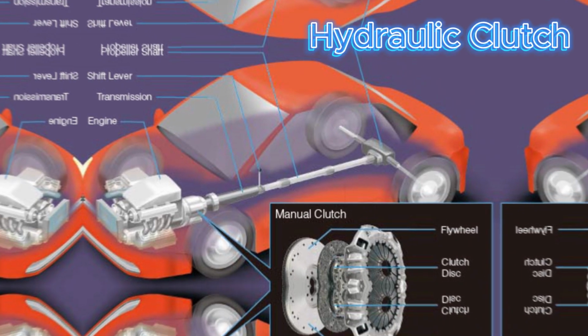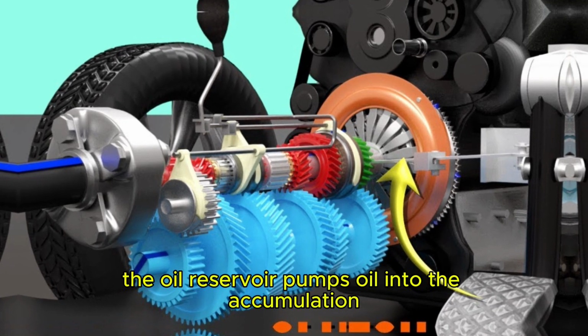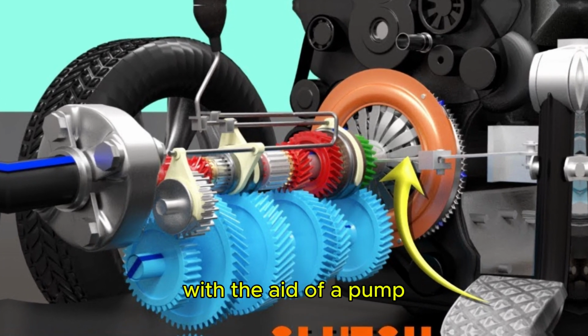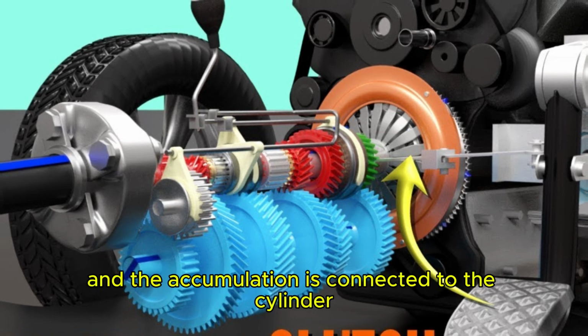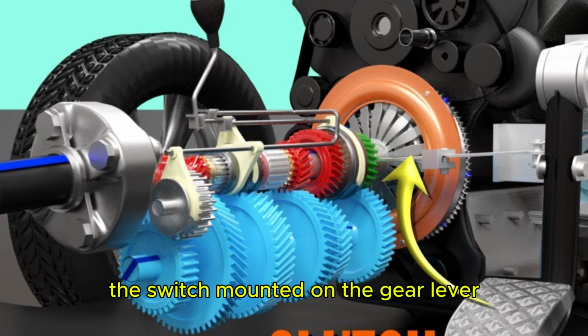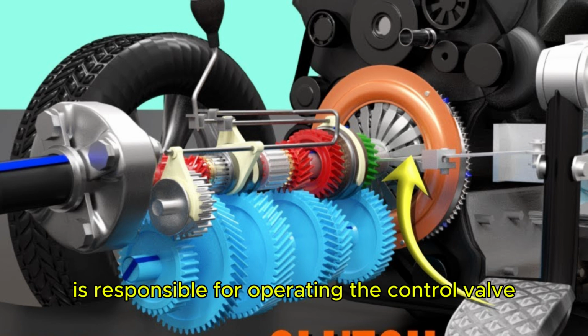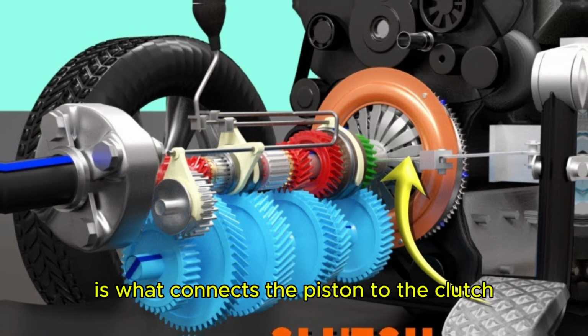Hydraulic clutch. In the working principle of a hydraulic clutch, the oil reservoir pumps oil into the accumulation with the aid of a pump. This pump works together with the engine, and the accumulation is connected to the cylinder through the control valve. The switch mounted on the gear lever is responsible for operating the control valve. The linkage mechanism is what connects the piston to the clutch.